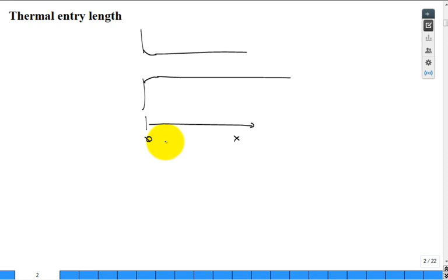We talked about that last time with the velocity profile. And now thermally fully developed. So I think it's easiest when you talk about developing a temperature profile to talk about a hot wall. What does T_s represent? The surface temperature of the wall. It could be constant. That's easy for students to conceptually think about. And the fluid out here may be all T infinity, a lower temperature, color-coded blue.